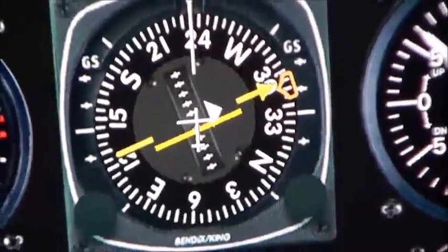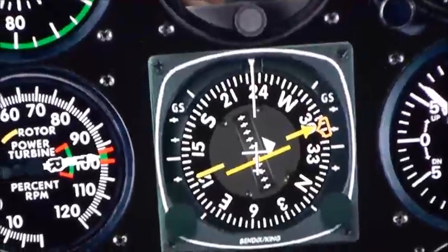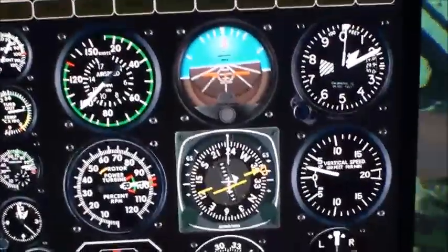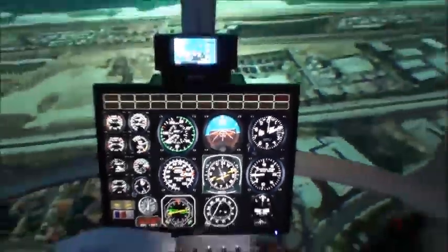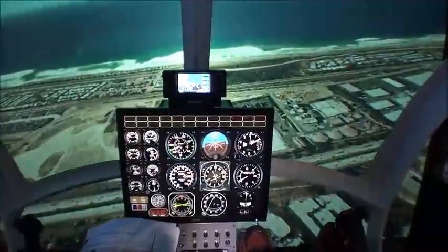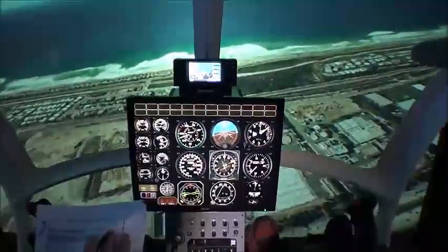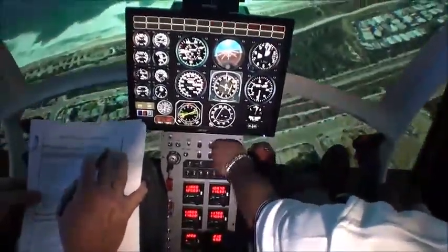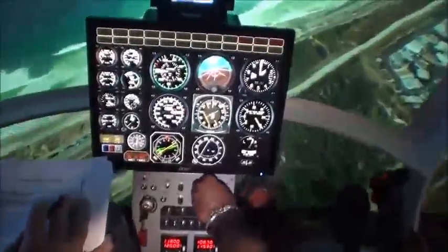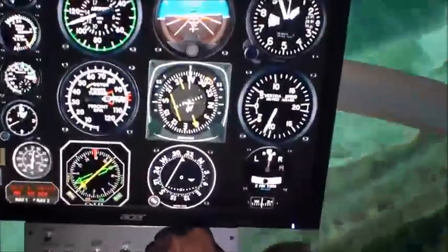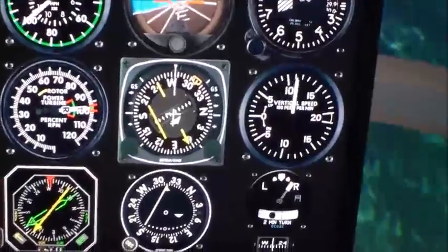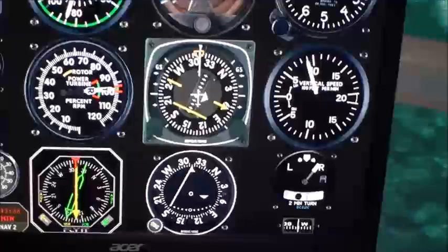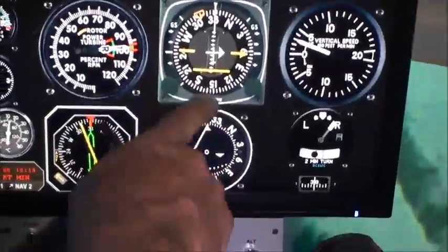So that you can see now for the ILS, we'll have to tune the localizer in, and we can do the back course because we don't need to go out on the other side of the airport. Okay, so I'll tune the 187 ILS in for the airport here. And remember, if we're on the back course, you fly away from the needle. That's this one. With this one, you don't have to.